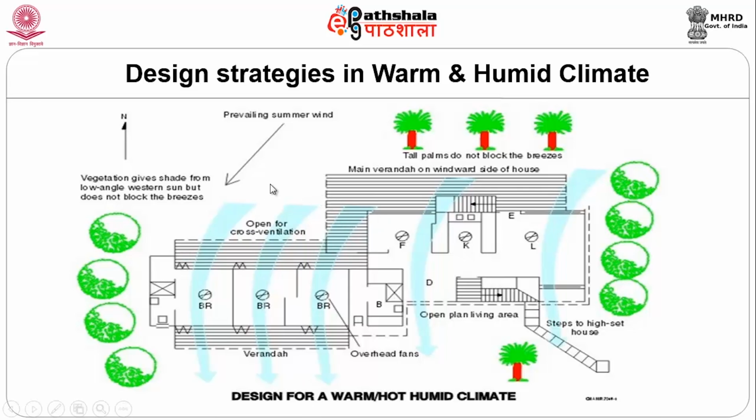We need to have open areas around with a veranda for cross ventilation and an open plan for the living area. Tall palms do not block the breezes, and a main veranda on the windward side of the house. And we need to have steps to high set the house or tilt the house, which means that you're going to bring air and breeze into the house. If you're not going to raise the height of your house, you will have thick cluttered air along the ground floor. As you raise the level of your house, there is more breeze, and the vegetation around will help move the breeze around.